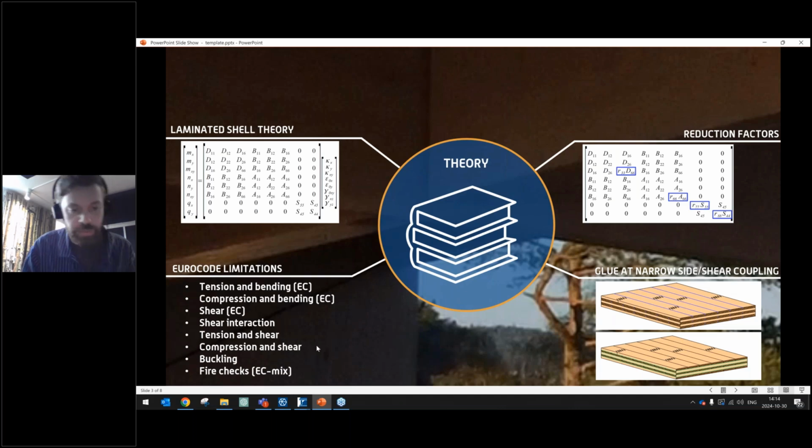However, in FEM-Design, we also have two other things, which is kind of unique, I would say. At least we were very early to implement this. The first thing is the buckling of CLT. This will calculate a corresponding area in an arbitrary direction. So it could be in either direction, basically, or a slanted direction. I will show that later on in the software, and calculate the buckling for this part of the CLT.